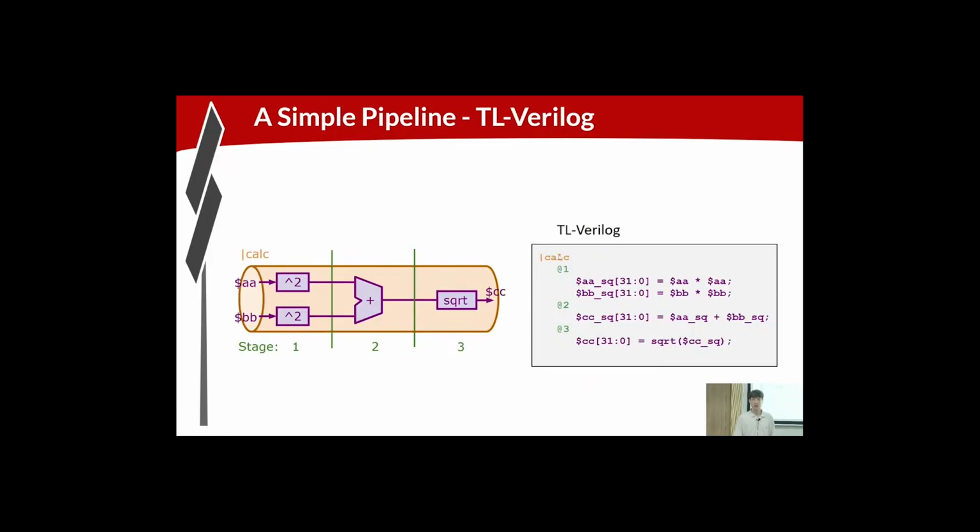You can very directly translate a diagram like this to code. Okay, so this is the syntax in TL Verilog. By placing your logic in context, you derive from the context the flip-flops. Okay. So in this representation of the pipeline logic, I'm not expressing the flip-flops explicitly. So that makes my logic not just easier to express, but easier to modify. And we'll see that coming up.